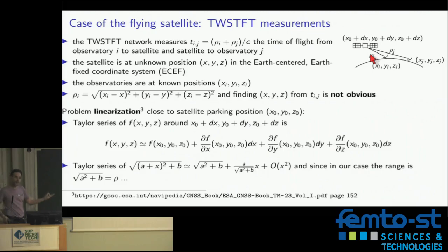And we want sub-nanoseconds. So of course, there's no way we're going to reach let's say sub-microsecond, at least if we don't cancel for satellite position. So that's the whole story about finding the satellite position. You want to cancel the fact that this satellite is moving around. These guys are fixed on the surface of the Earth, and by moving around, well, you introduce some delay, and if you want to do time transfer, you need to remove this delay, and the only way I'm familiar with is to estimate the position of a satellite.